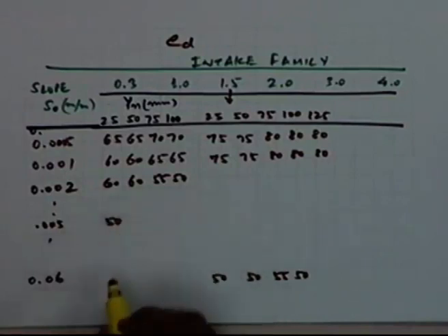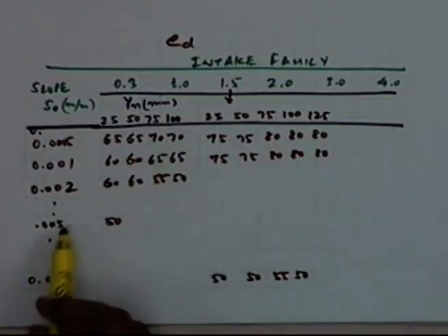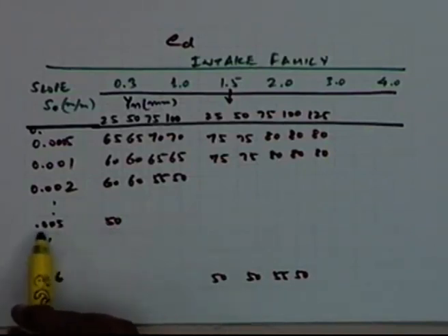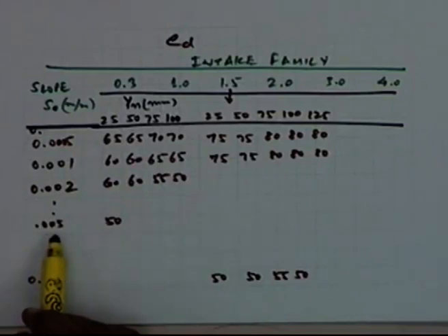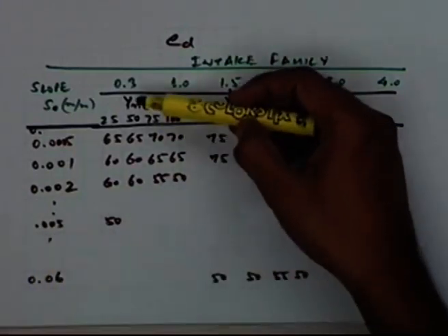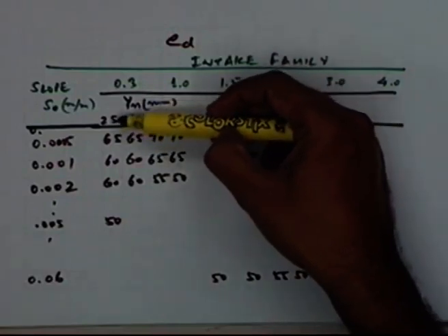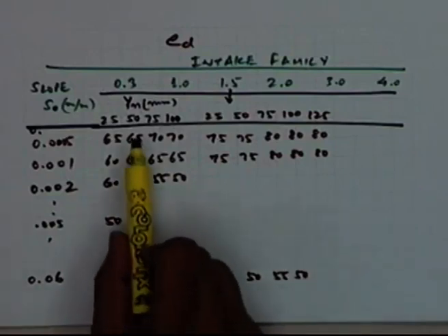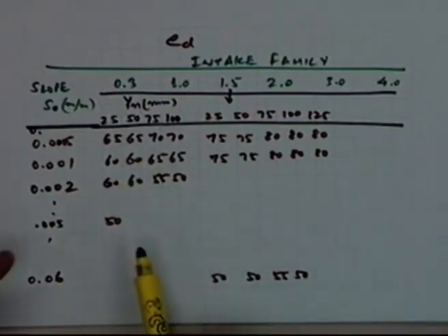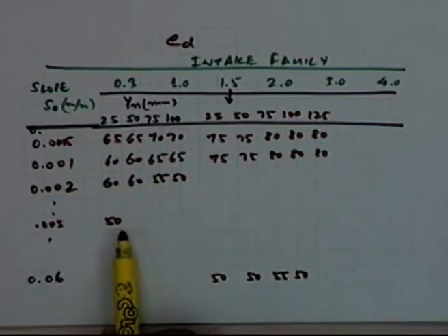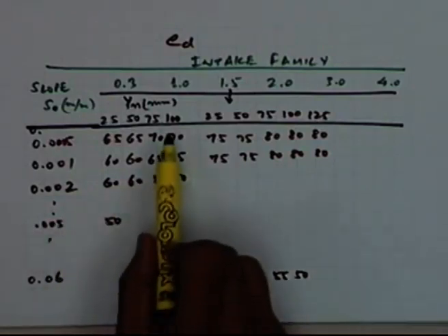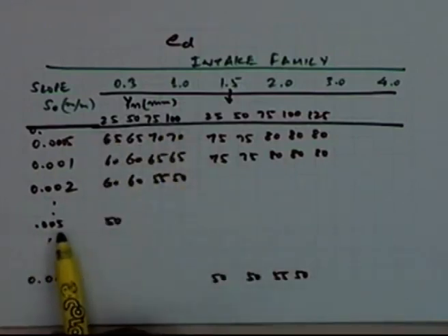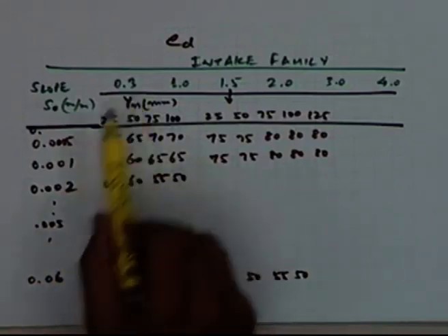the value of 50% efficiency is achievable when you have a slope of 0.5% and the depth to be applied is 25 millimeters. Okay. You might not be able to get an efficiency which is even 50% if you try to apply a depth which is more than 25 millimeters with such a slope and with such a family of the soil.